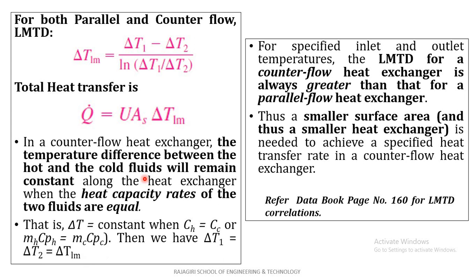In the case of a parallel flow heat exchanger, delta T1 is never equal to delta T2. The LMTD for a counterflow heat exchanger is always greater than that of a parallel flow heat exchanger for specified inlet and outlet temperatures. You can verify it by applying some values. Always the counterflow heat exchanger LMTD is higher than the parallel flow heat exchanger LMTD.